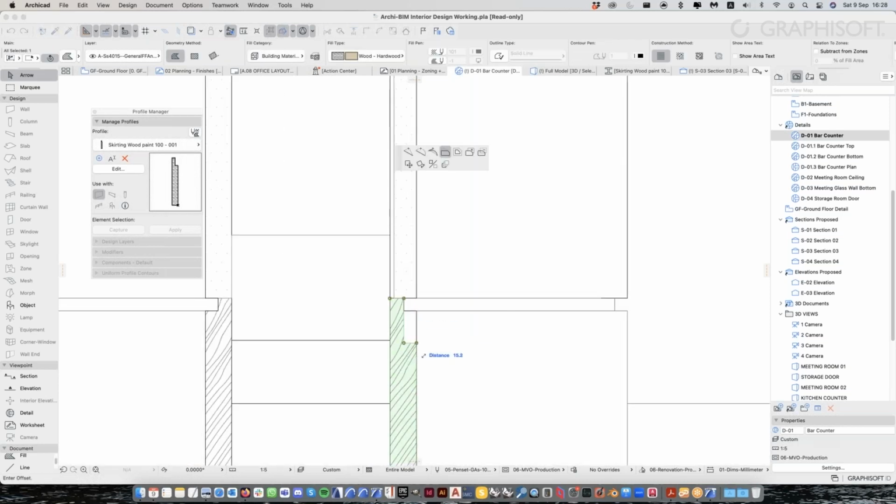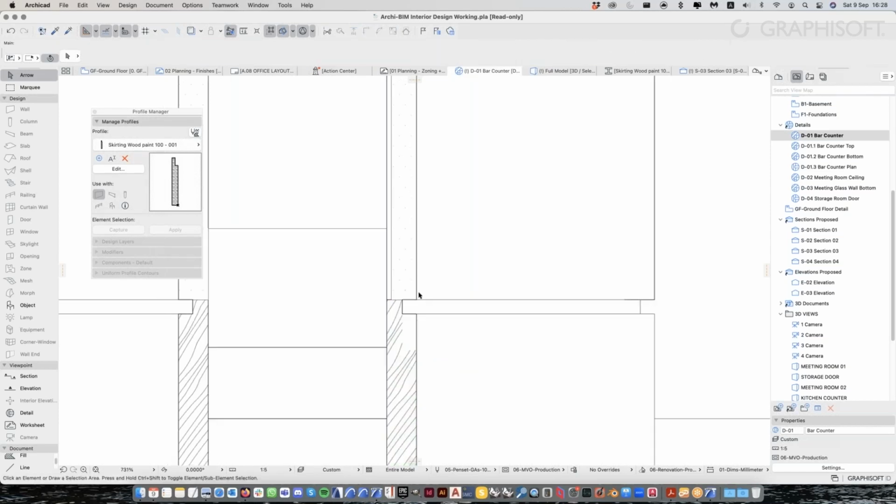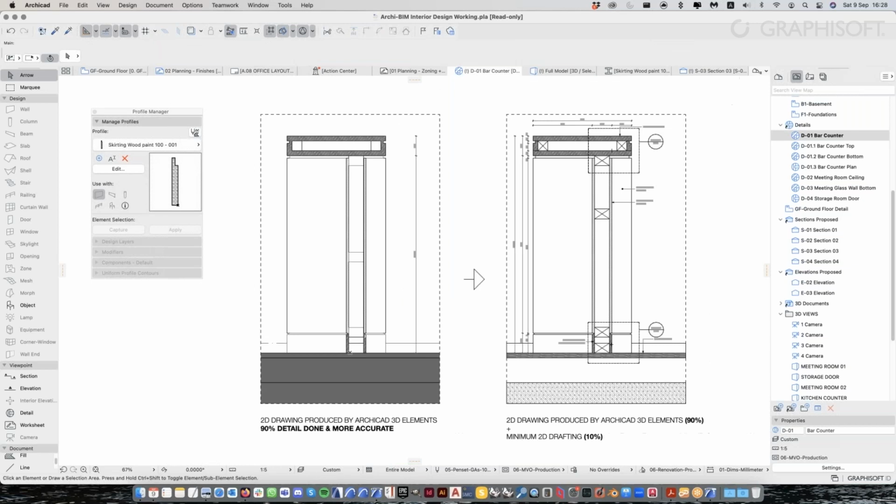It's not going to keep that change. It will just update back to what it was. So usually what I do is once I have created a marker, a detail, I copy it to the side and do my actual adjustments on the side, so that when you rebuild things, it's not going to undo what I did.